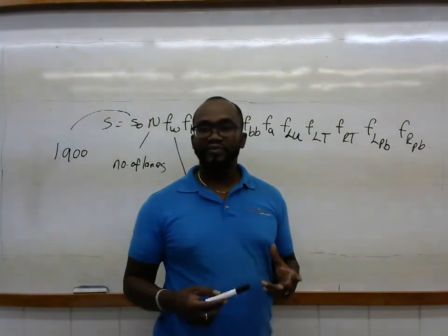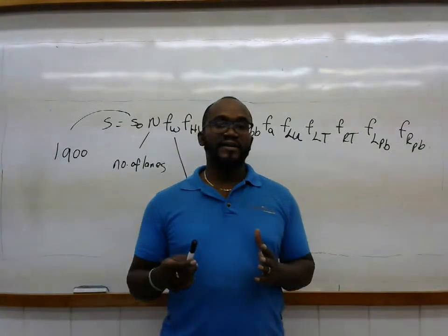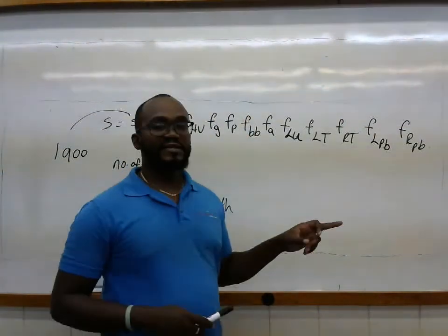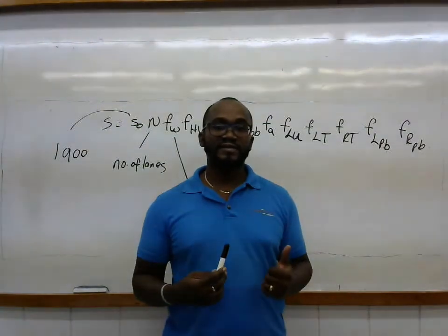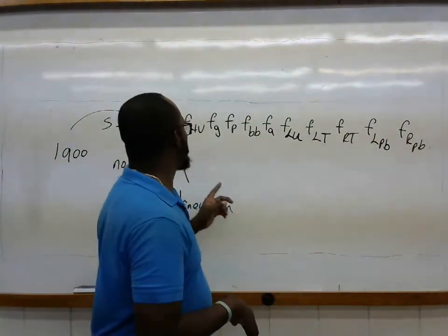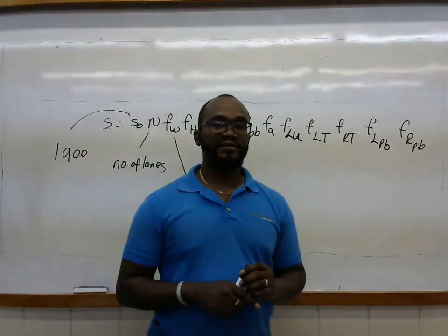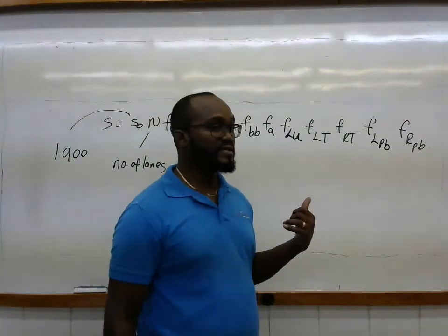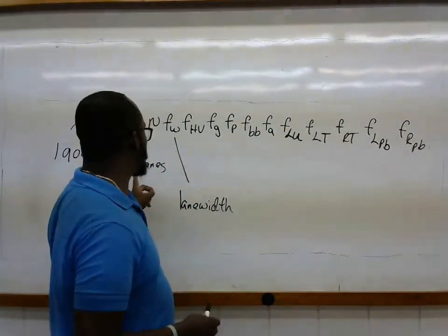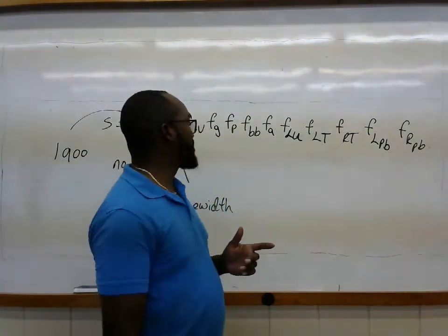So in other words, what the Highway Capacity Manual is suggesting is that the ability to move through an intersection is also dependent on the width of the lanes. So the narrower the lanes, you can imagine the less ability to proceed through the intersection. The wider the lanes, the more the ability, or the quicker you can go through the intersection. Or in this particular case, the more vehicles that can proceed through the intersection.